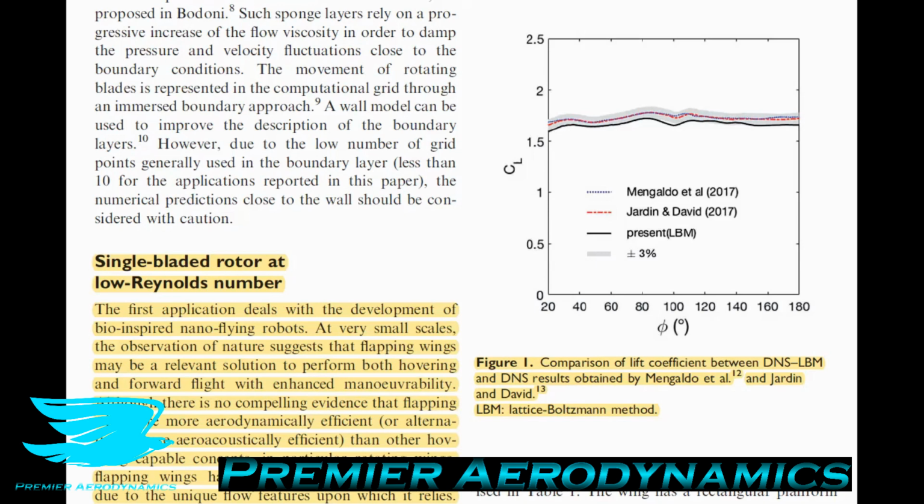So in other words, they looked at the Lattice Boltzmann method, they compared it to Navier-Stokes CFD. First of all, they found that the instantaneous lift production mimics very closely the instantaneous production that they found from other CFD methods. However, it's just offset by 3% for some reason. So that's quite interesting. They also looked at refining the grids to see how the grid resolution, as you do with Navier-Stokes CFD, affects the lift production. And they looked at 3 different resolutions.